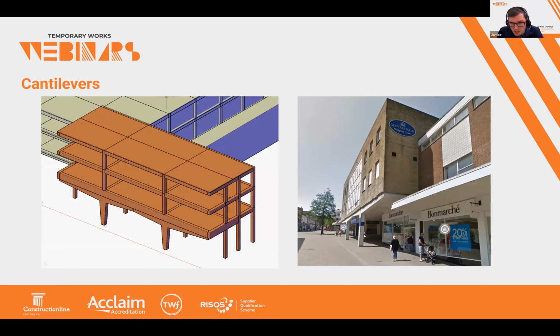You can see at the front we've got these large columns with sort of balanced cantilevers on them, and on the sides of the structure also large cantilevering beams. So you'd have one compression leg with the closer one to the edge, and the rear leg here would be in tension to sort of balance the forces.